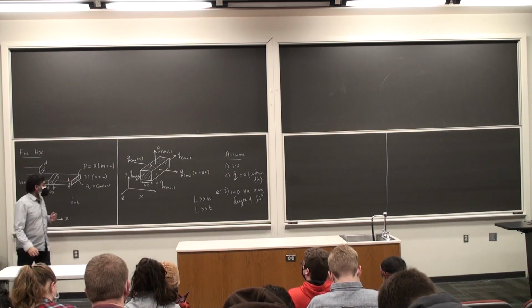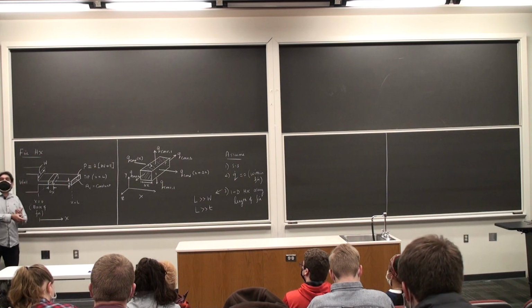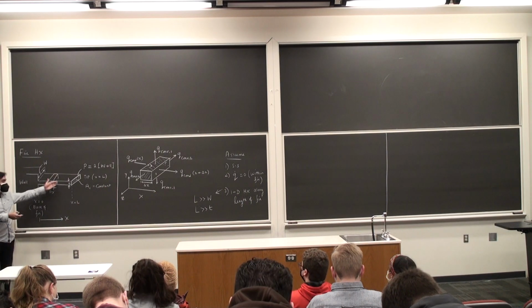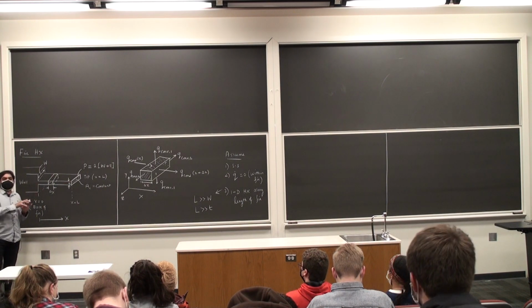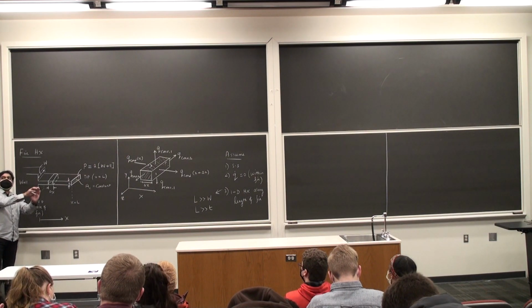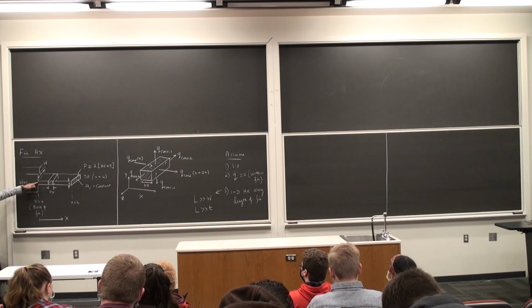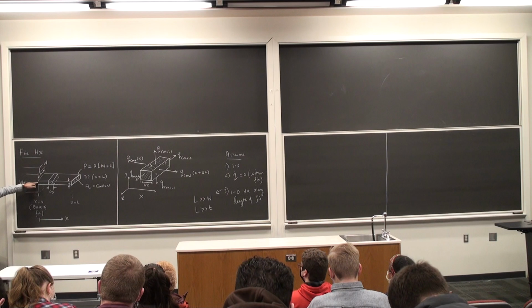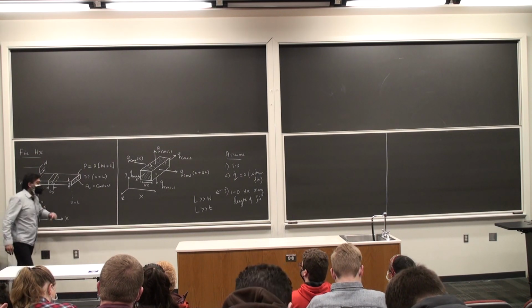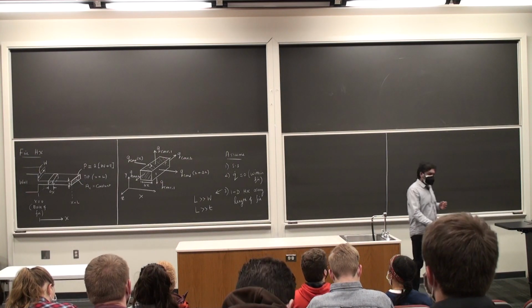And as a matter of fact, the thermal conductivity of a fin is also supposed to be fairly large, and the reason for that is to ensure that the temperature drop across the length of the fin is reasonably small. If the temperature drop along the length of the fin is reasonably small, it is approximately as if the whole fin is at the temperature of the base, so that I have the maximum heat transfer possible from the fin onto the atmosphere. We will look at these subtleties very soon. So these are our assumptions.